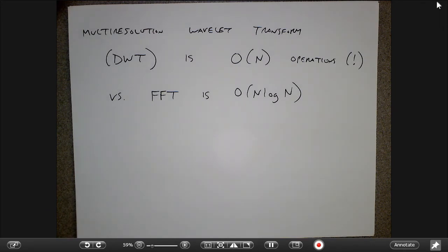If you want a steady light in the room, your eye is not sensitive to changes that occur much above some critical frequency, like 60 hertz. So if we modulate the lights at hundreds or thousands of hertz, we can use that to communicate digital information. And you can imagine that each light in this room might be communicating slightly different information to different people in the room.